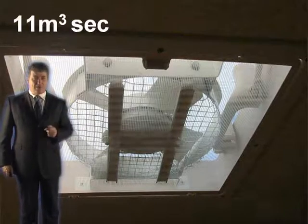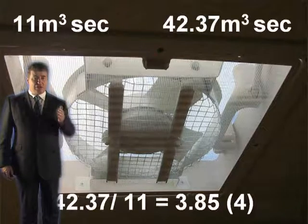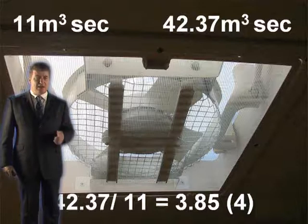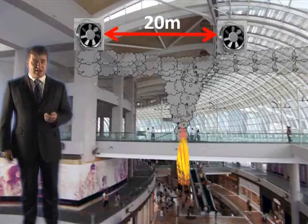Now we know the volumetric flow rate is 11 metres cubed a second. If you divide it out, you've got 42.37 divided by 11. Therefore, you need 3.85, or you need 4 fans. So we need 4 fans in that reservoir with an output of 11 metres cubed a second. That covers step 7. Let's move on to step 8, which is the stagnation check.